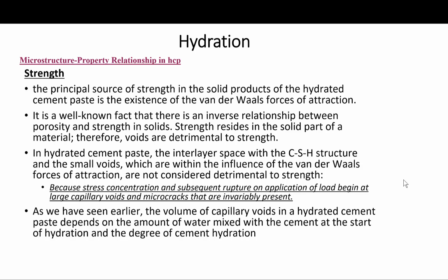In the hydrated cement paste, the interlayer space within the calcium silicate hydrate structure and the small voids within the influence of the van der Waals forces of attraction are not considered detrimental to strength. So you have to keep that in mind and go back and look at some of the slides in the previous lectures to refresh.